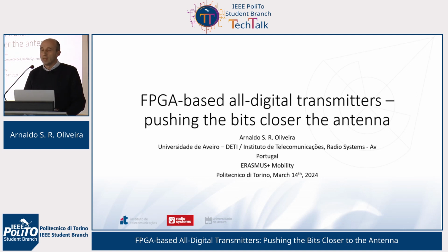In this talk I will summarize our work on FPGA all-digital transmitters, which is a different way of looking into the design of RF transmitters. We try to push as much as possible to bits close to the antennas, which means that the digital processing is pushed as close as possible to the radiating element.